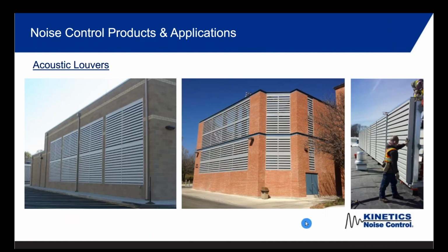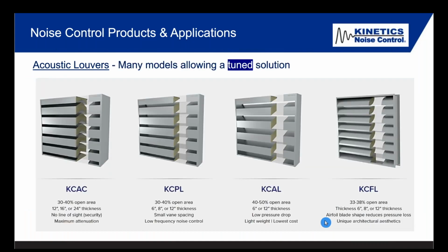Acoustic louvers, I love them. They're stubby ventilation silencers, typically anywhere between 4-inch deep to 24-inch deep, whether it's a generator room and you're filling the holes, whether it's an equipment yard, no top for cooling towers, or sometimes it's equipment on the roof and the architect really likes the look of these horizontal lines. So instead of using a solid barrier wall panel, they use that.